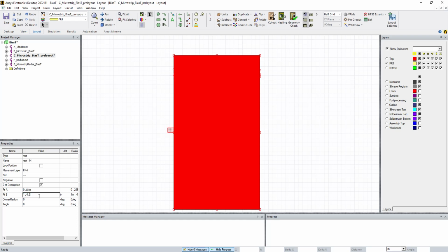And then what we're going to do is say, so that defines this point. Let's go over to this guy down here. So we're going to make this thing the width of the PCB wide. So WPCB wide, comma, minus LPCB minus WCO.